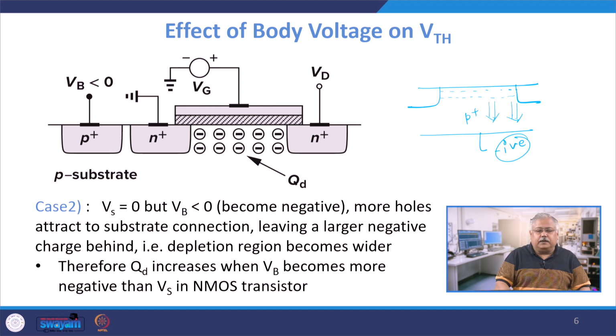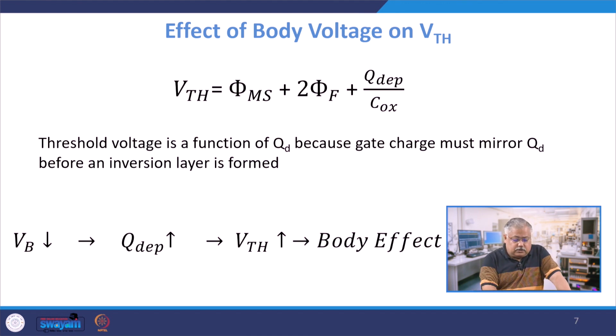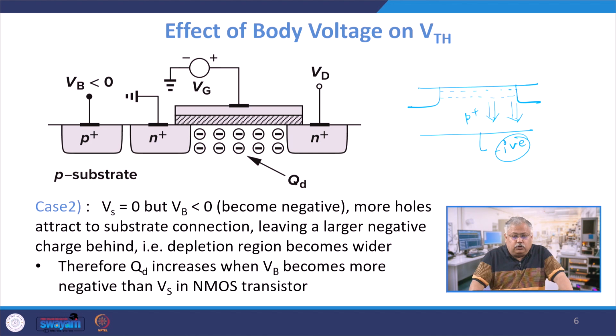That is what is written there, which means that the number of depletion fixed charges becomes more and more when Vb becomes more and more negative. If I go on increasing the negative value of the substrate bias, I introduce more and more depletion region near the silicon dioxide interface. So that region goes on becoming increasingly more depleted. Let me go back to that stage and explain to you now from that angle.